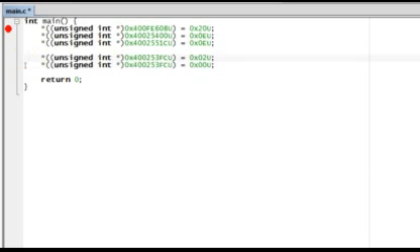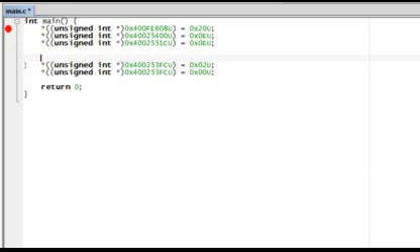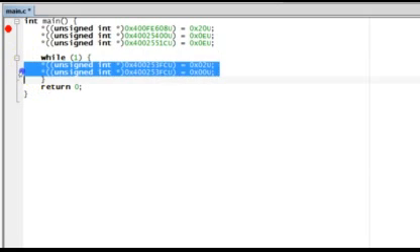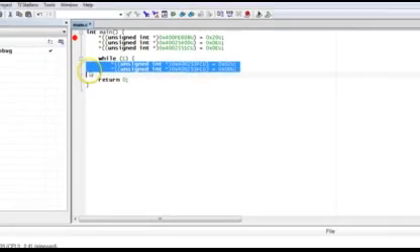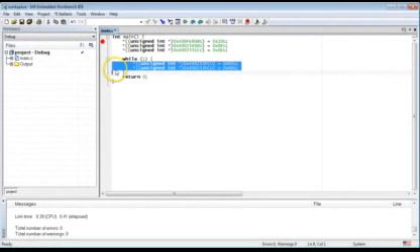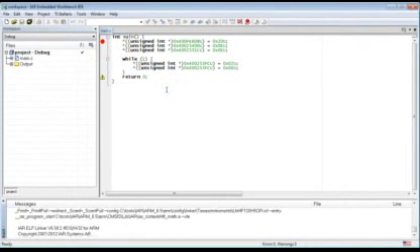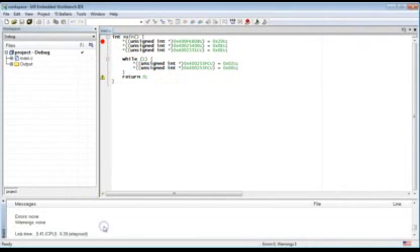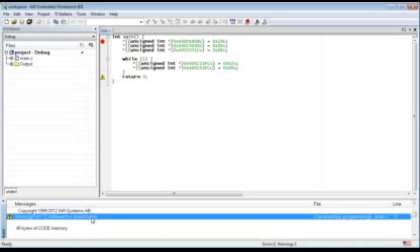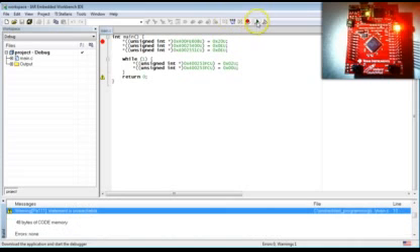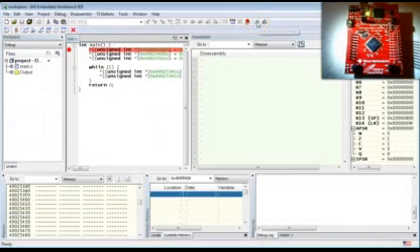Actually, if you want to really blink the LED, you can't turn it on and off just once, but you need to keep doing this forever. To achieve this, you can wrap a while loop around the code for turning the LED on and off. The constant 1 in place of the condition means that the condition is always true, so the loop runs forever. When you compile this code, you get a warning that the return statement downstream from the endless while is unreachable, which is true. Let's test this code on the Launchpad board.